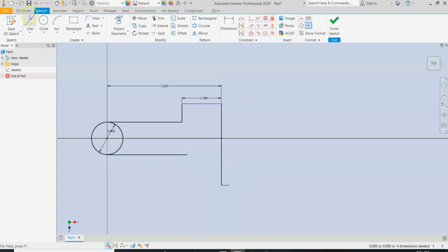Oh well, let me just start over with that. I'm going to draw another line here and up to here, and we'll fix that and then get rid of that line. There we go. Sometimes that happens. Usually if you start out with your problem being a little bit more to the actual size of the part, those dimension constraints, when you adjust them, will be a little bit more forgiving. This one wasn't forgiving at all, so I apologize for that.